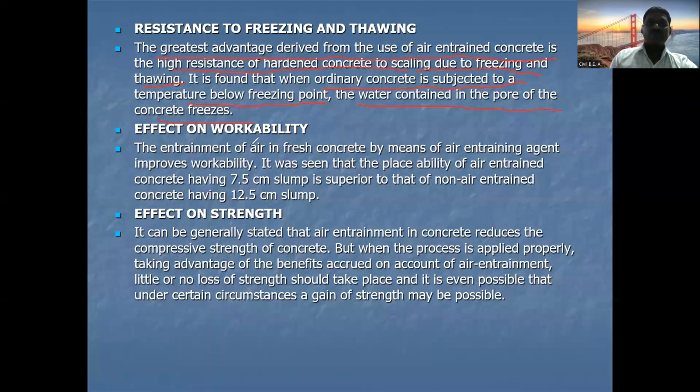So this is one of the effects. Then the effect on workability. If we add the air entraining agent, what is the effect on workability? Generally, if we add the air entraining agent into the concrete, the entrainment of air in fresh concrete improves the workability. As I told you, the workability of concrete is improved if we add air entrainment.